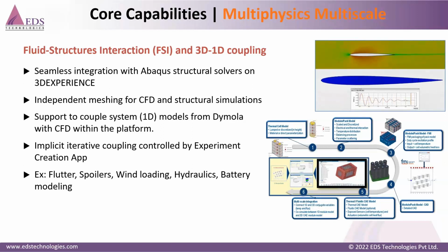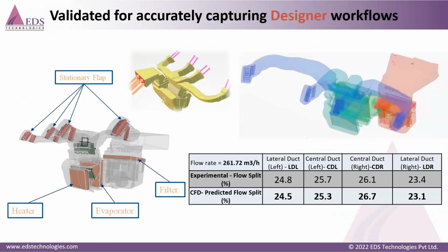And finally, these can be combined to have combined results. We also support coupled systems, that is 1D models from Dymola. Dymola is another one of our tools for 1D simulations, and that can be seamlessly integrated with the CFD within the platform to have a 1D-3D coupled CFD analysis, as well as implicit iterative coupling, which is controlled by the experiment creation app, wherein you can define and create different types of studies or experiments using the experiment creation apps.